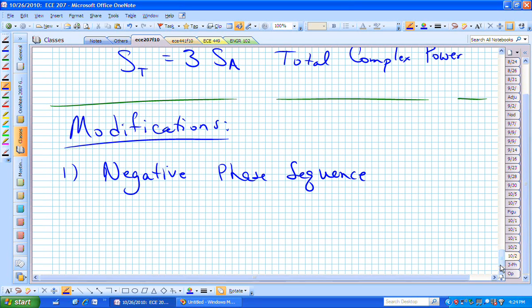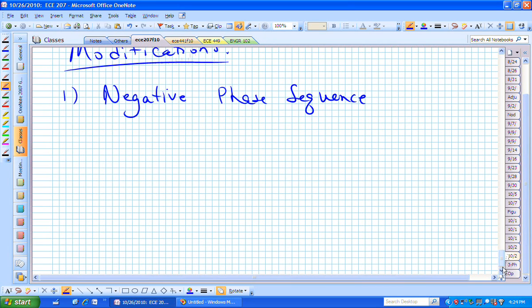What is this? What's the positive phase sequence? No, the positive phase sequence doesn't have to be inductive. It could be capacitive. It could be either. The positive phase sequence just means the relationship between the A phase, the B phase, and the C phase. And you know if you're standing here watching them spin around you in a counterclockwise fashion, A is going to hit you first, B is going to be next, and C is going to be last. That's a positive. If it's negative, it just changes B and C, meaning now you have an ACB.